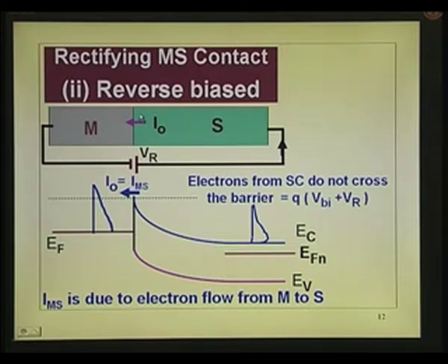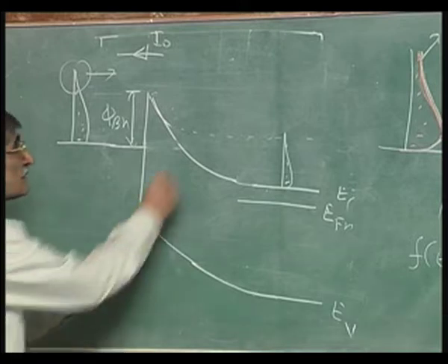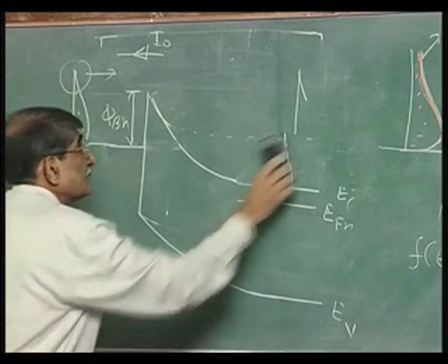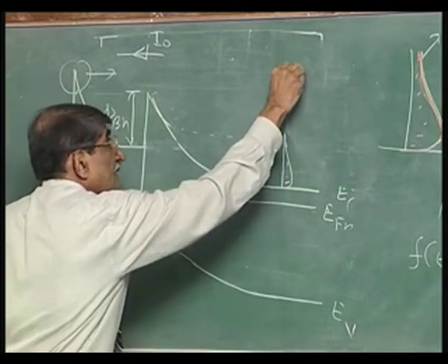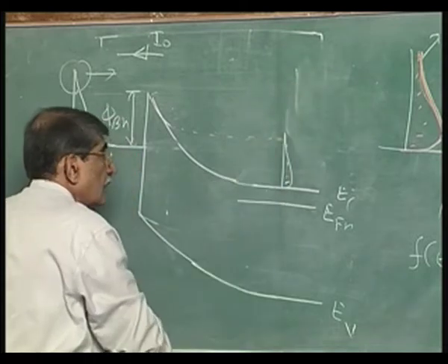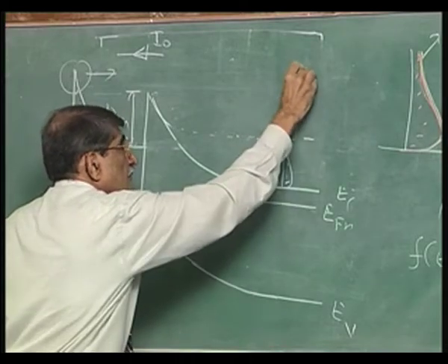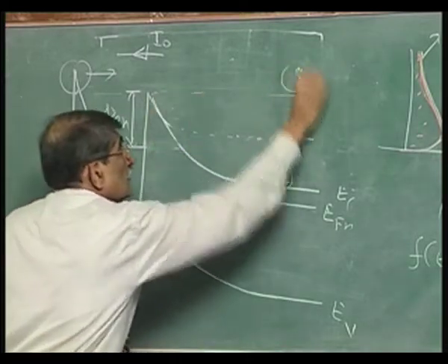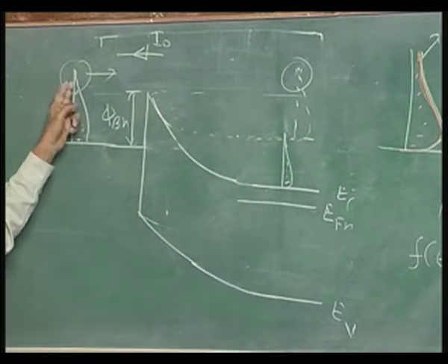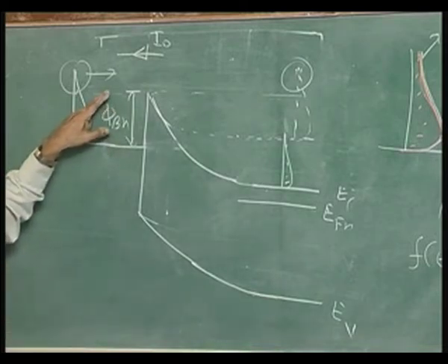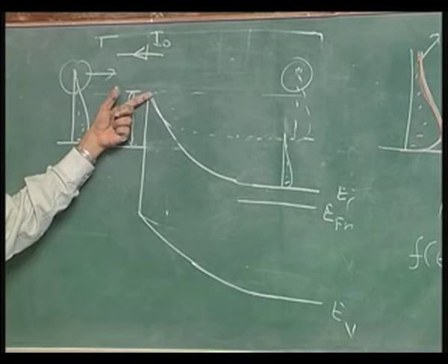Okay. What happens to the current which was flowing from the semiconductor to the metal? You have pulled the potential energy down here. Originally when it was here, they were having energy like this. Let me draw it by dotted line before that. You had this energy band diagram like this. Those were the ones which were compensating for that thermal equilibrium condition to make the current equal to 0. Okay. Now, this current has not changed, I naught.